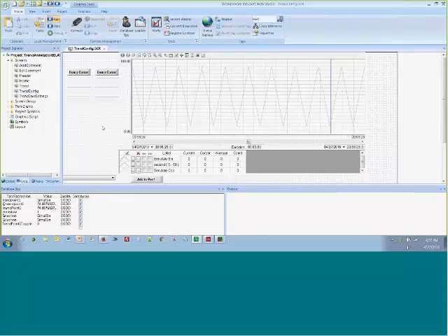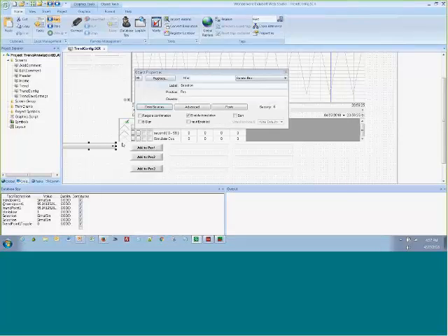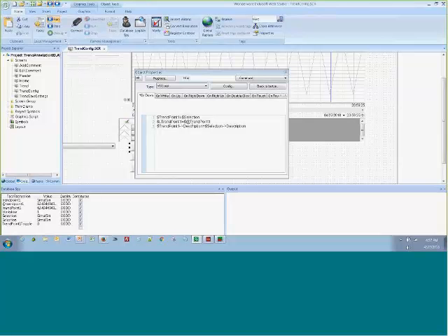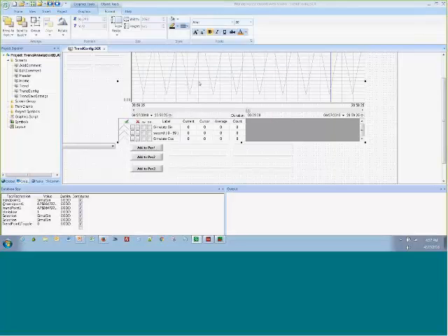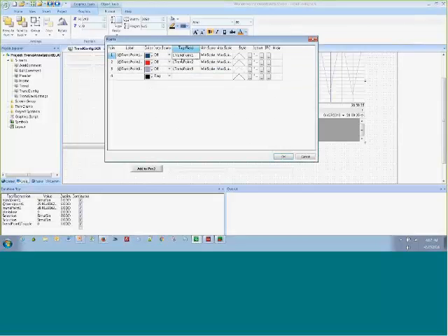So what's happening here is I have this drop down that provides you with the selection in here. That selection actually gets the name of that label. And then what we do is we take that selection and, using indirect addressing, write to this thing called ltrend.1. And then if we look in the trend, here's where it uses ltrend.1. So I'm using indirect addressing to then configure these 3 pens. And you could do this and add multiple. It doesn't have to be 3. It could be more than 3.